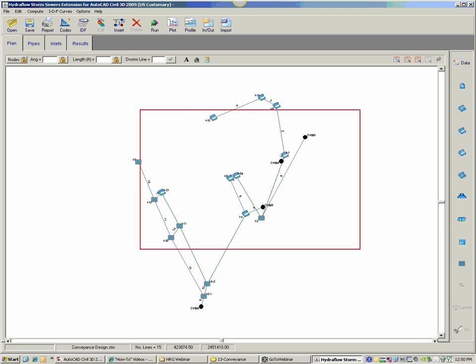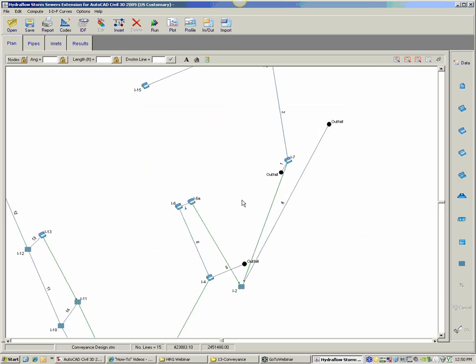You can see in this initial iteration that we did, we don't actually have the I-20 or I-20 and 20A up there. I brought this data in before the class and designed it all up, but I didn't have this I-20, 20A. So maybe adding the I-20 and 20A was a revision. So how do I get that into here now? Well, with Civil 3D, you can now round trip the data as much as you want with this Excel spreadsheet that Brandon Harder generated. So let's go ahead and do that.